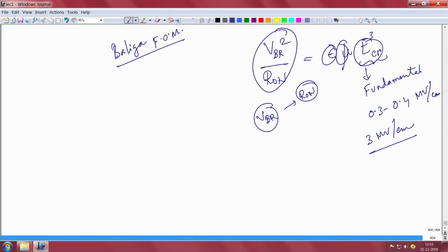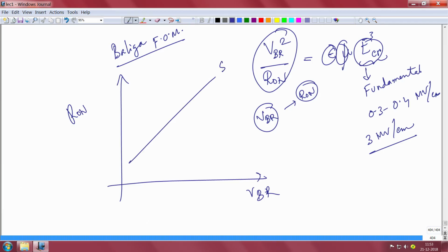You cannot get the best of both, and you can actually plot this same thing, the on resistance versus the breakdown voltage, and this gives you lines like this for silicon, for example. Then there's this technology, gallium nitride, which is over here. So for a given on resistance, say 1 milliohm or so, you can get a breakdown of silicon of some 100 volt. Maybe in gallium nitride you can get 1000 volt, which means for the same current you are actually getting much higher blocking voltage in a wide bandgap technology like gallium nitride. That's why the promise of gallium nitride and other technologies comes up here.